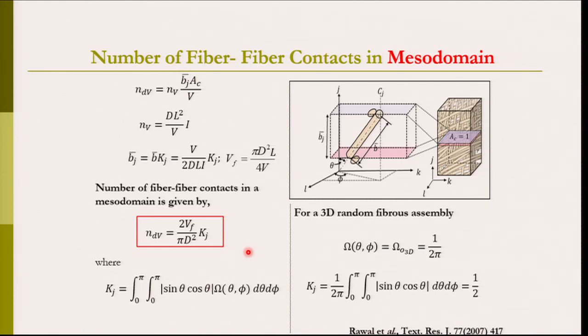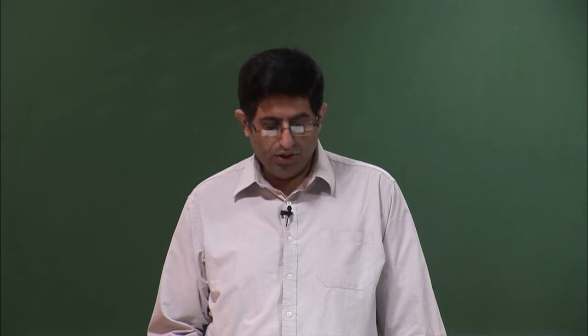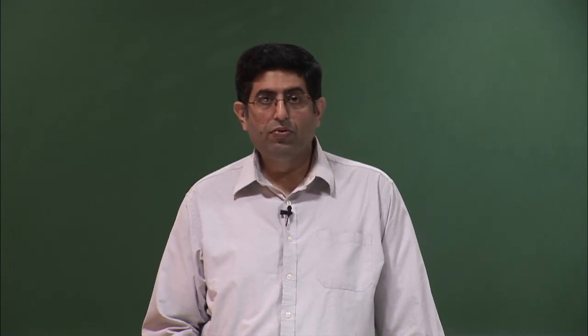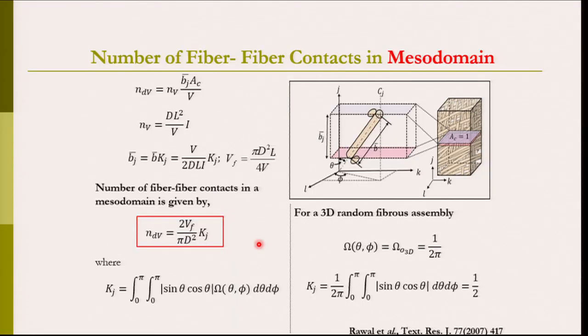In the next series of lectures you will see that we will be making use of NdV, because it is a useful approach for calculating the number of fiber to fiber contacts in a meso domain, because this meso domain would experience the same level of strain, for example, in tensile loading or in compression loading, and it would reflect the strain experienced by the fibrous assembly or fibrous material.